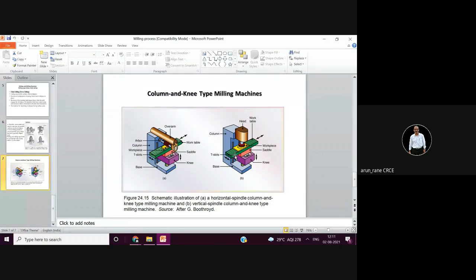So to make the design of the machine simpler, that time we go for a fixed bed type machine. Very important question from Y1. In a fixed bed type machine, your bed is not moving, your bed is stationary. All the X, Y, Z movements are given to the cutter, and of course the cutter is rotating. Fixed bed type machines are used for machining heavy components.